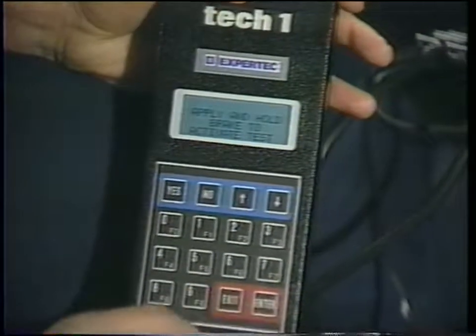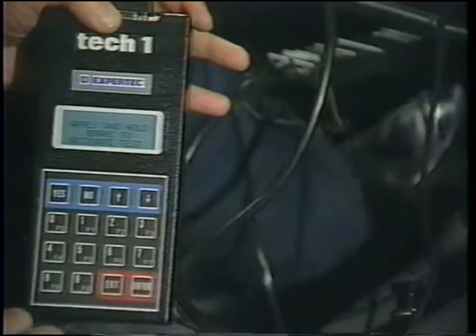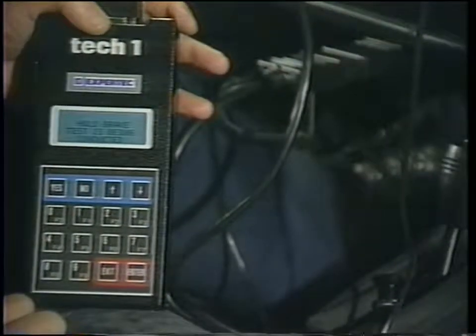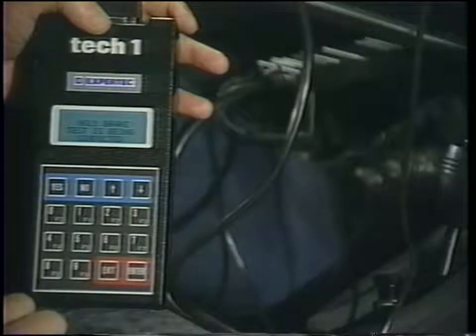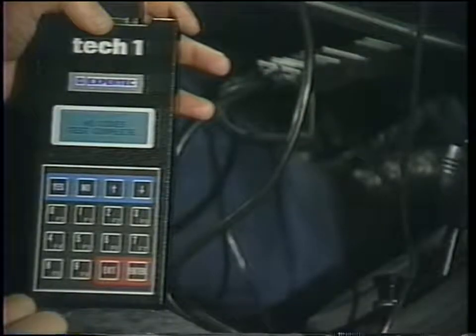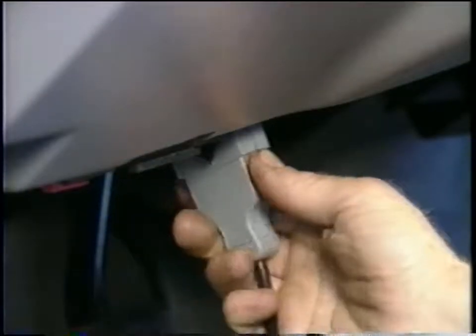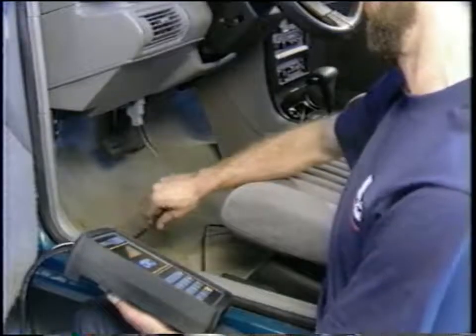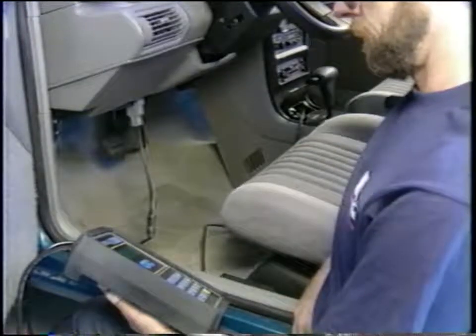On other applications, such as Kelsey-Hayes 4WAL, a scan tool must be used to cycle the ABS solenoids in the modulator on and off to get air out of the unit. On Delco ABS 6 applications, a scan tool is also needed to home the rear pistons in the modulator. If this is not done, the rear brake lines cannot be bled.